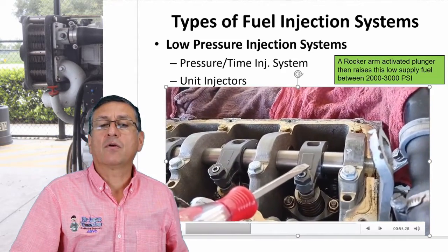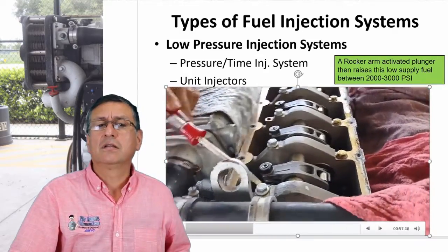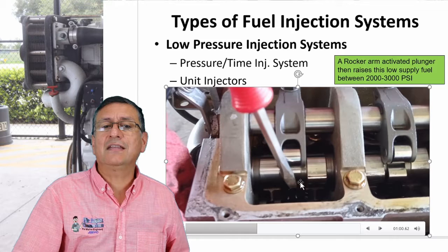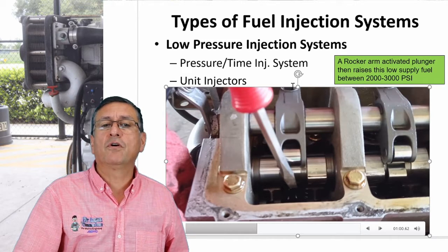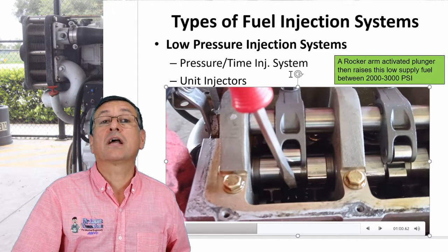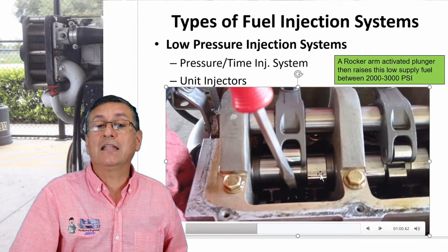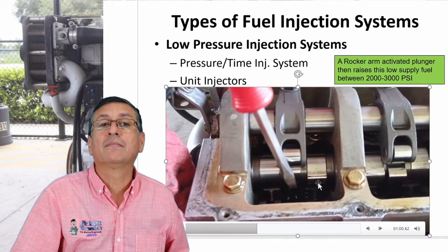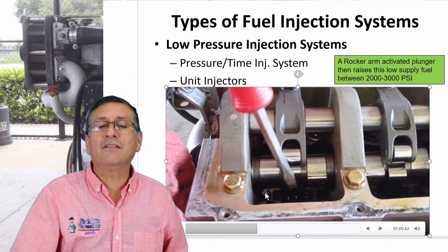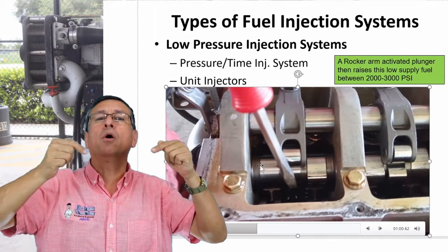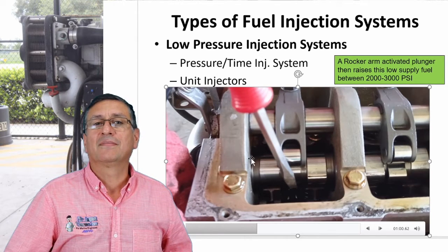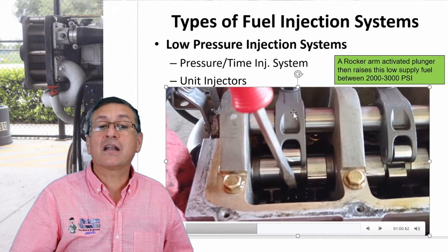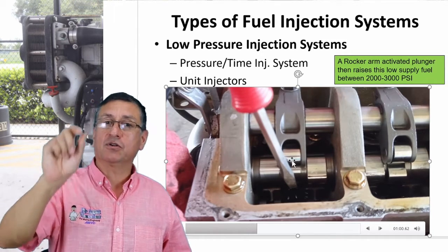Okay, that's the rocker arm for the injector. And on this side, this is the camshaft. One lobe for this rocker arm dedicated to the injector, and the other lobes compress the valves directly. Those valves are compressed directly by the lobes of the camshaft. Yeah, the valves don't use rocker arms. This rocker arm is exclusive for the injector.